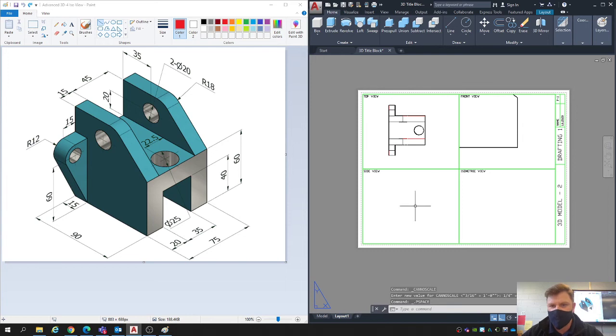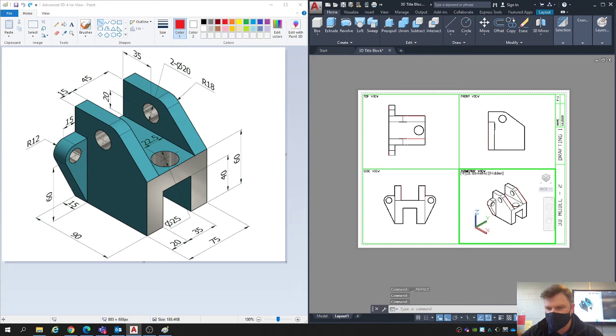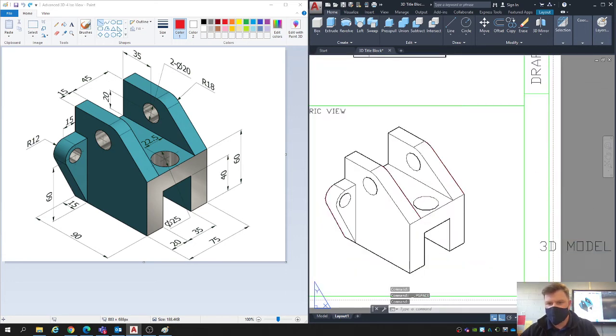And then double click out, double click to the side view, find your object, click down here, set it to 1/4, get it about in the center. Front view, zoom out, set the front, yeah, I guess that would be the front. Set that to 1/4, move it over, double click out, isometric view. This one might not fit at 1/4. Sometimes isometric ones don't. We'll try it anyway. Oh, it does. Okay. So this is Advanced 3D Model 4.